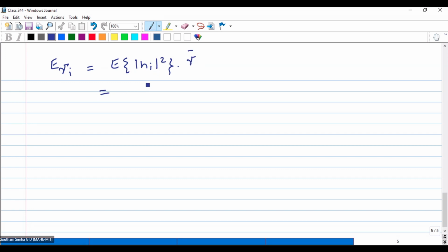So that will be the signal strength based on the signature of the channel. Okay, and I will have one expectation of |h|^2 for Rayleigh fading. This becomes equal to 1. What I'll get is the expectation of gamma_i is equal to gamma bar for a Rayleigh distributed function. Now you can also calculate the outage probability based on this.